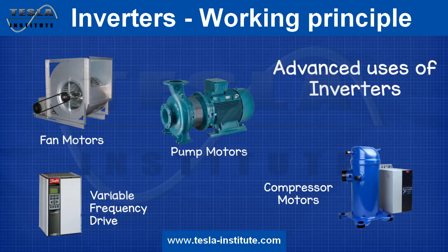A slightly more complex way they are used is when integrated into variable frequency drives or variable speed drives to control the speed, the torque and the direction of AC motors in order to achieve very precise control which saves energy. You'll find these on fans, pumps and compressors, and basically any equipment which rotates. They are used in all industries, but extensively within HVAC systems for industrial and commercial properties.